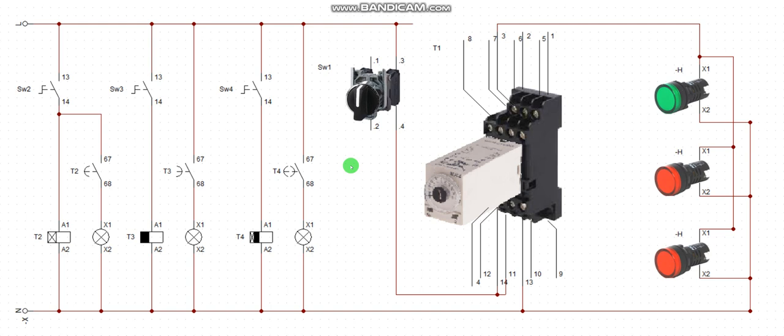For instance, I'll give you an example. You want to design an ATS. You put up the instruction that once this power is available, please activate my load. When this power has been working for a preset time, please shut it down and activate the second, the generator, to come up. So that instruction will be embedded in timers and sensors. Sensors, timers and other multi-controllers and modulars will do their function right inside the ATS.